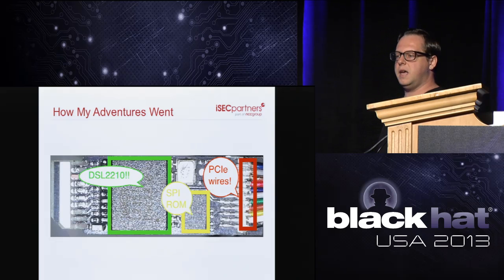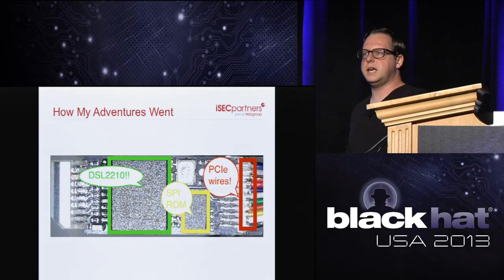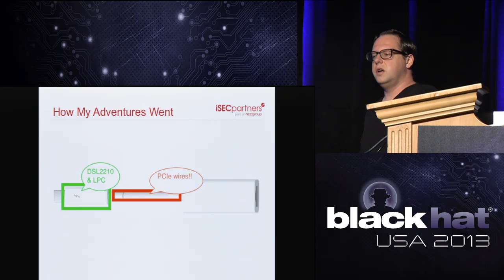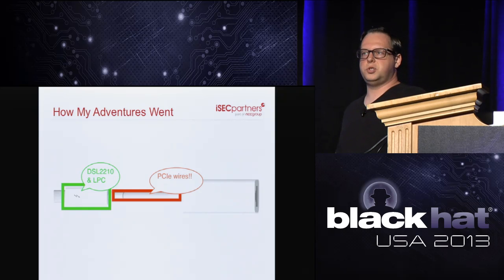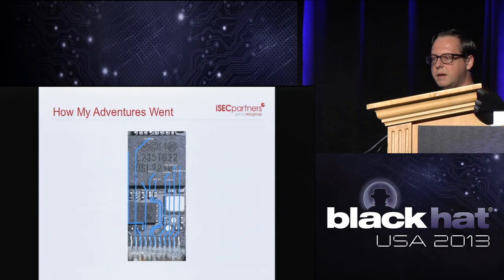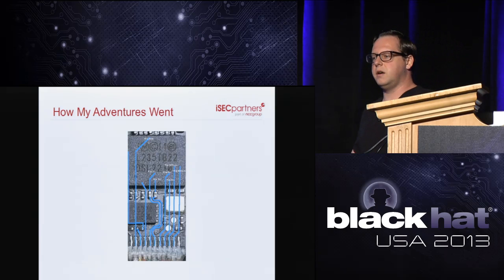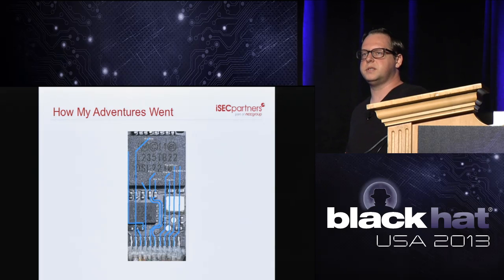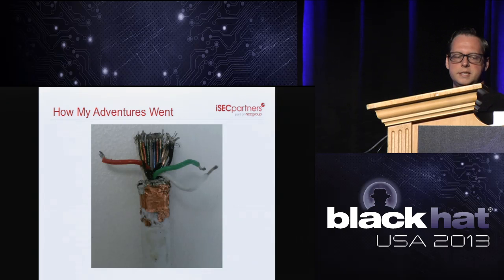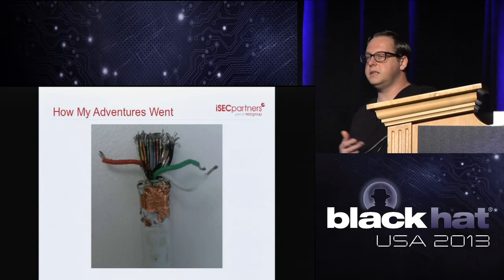We've also mapped out that the wires coming out of the device are PCI Express lines. So coming out of the connector down this wire, it's just straight PCI Express. And we know from our reverse engineering what pins are doing what and what's going on. So we can start making a map on this device as well. We could say, okay, I've mapped out all the PCI Express pins. These are the wires that are doing this PCI Express. And so what we can do is take this and desolder it.